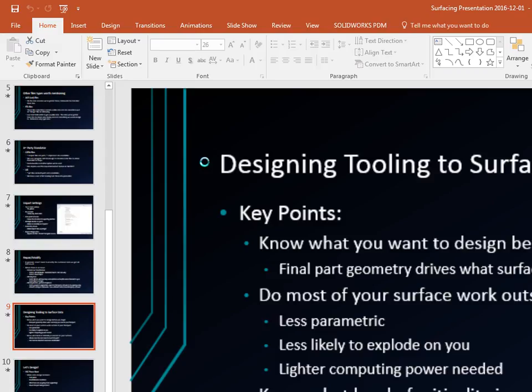Now I think untrimmed surface will actually work if it's over 2 faces, but quite often you end up with a blue line, a non-joined edge in the center of it. So be aware of that. You might have to either knit it or round trip it as an IGES.